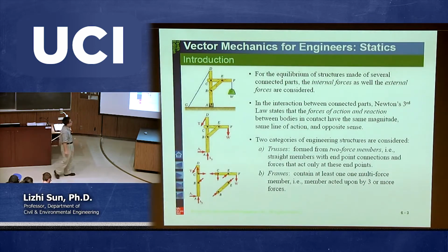So in order to calculate internal forces, we have to make the further cut. For example, if we want to cut somewhere between B and E, and then we cut somewhere also towards E direction, but close to E, then we're going to separate this part of the 3D body, which is a slender member, from the rest of the 3D body.